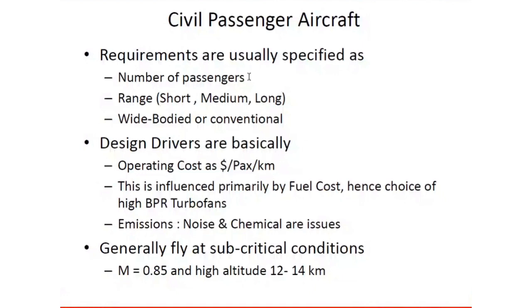Here, the design drivers, what really matters to a civil passenger aircraft operator or manufacturer is the operating cost, dollars per passenger per kilometer. And this is of course influenced by the fuel cost. Hence, a choice of high bypass turbofans is absolutely essential. There you have no choice. Unless you go for high bypass turbofans, you will not be able to meet the operating cost. So the moment you say passenger aircraft, high bypass turbofans automatically pick themselves.